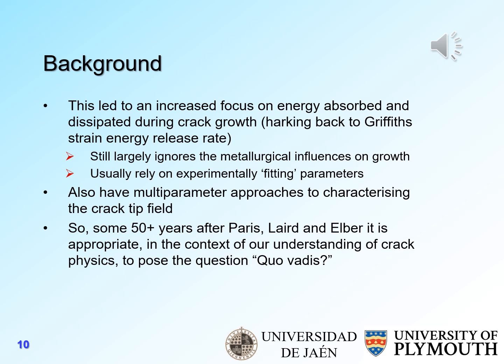These unresolved issues have led to an increased focus on other parameters to characterize fracture, such as the absorbed energy, and the energy that might be absorbed and dissipated during crack growth, which of course harks back to the Griffith strain energy release rate. However, energy approaches still largely ignore the metallurgical influences on crack growth and often rely on experimental fitting parameters. You've also had multi-parameter approaches to characterizing the crack tip field in recent years, but it seems to me that some 50 plus years after Paris, Laird and Elber, it's appropriate in the context of our understanding of crack physics to pose the question, quo vadis, where are we going?